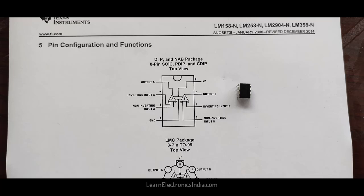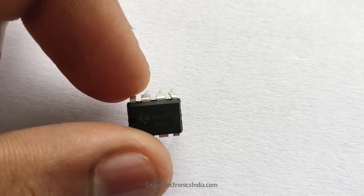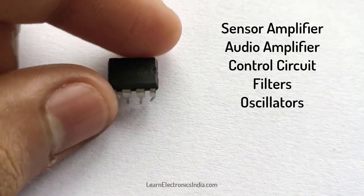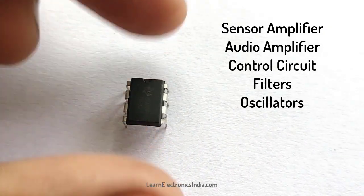An interesting feature of LM358 is that it uses only a single power supply to power both the op-amps. Pin 8 and pin 4 are the supply voltage pins. LM358 is used in various applications like sensor amplifier, audio amplifier, and control circuits where the op-amp can be used with a single power supply.